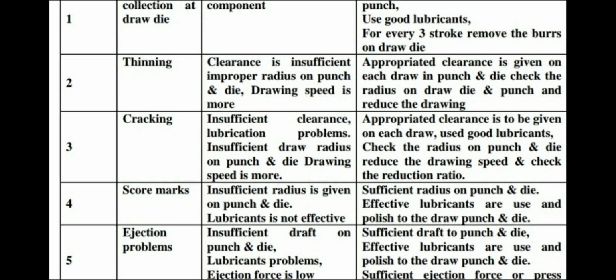The next defect is ejection problem. So insufficient draft on punch and die. So lubricant problem, the ejection force is low in case of some applications. And so what is the remedy? Sufficient draft to punch and die should be prepared. Effective lubricants are used and the draw punch and dies are polished.